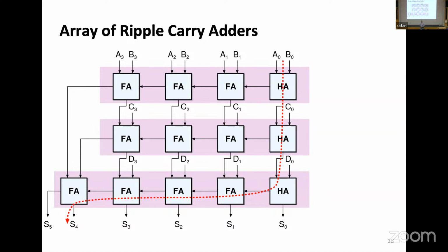It is part of the, let's say, design process. When you use these tools that generate it, they can analyze the delays, because every one of these blocks has a propagation delay and a contamination delay, and they add up. So you can use a tool which we call static timing analysis, meaning that we are not dynamically changing things given the inputs at some time. He can calculate it, and essentially, when you use a tool, in the end, he's going to say, you know what, you have to wait 4.5 nanoseconds until this circuit finishes.